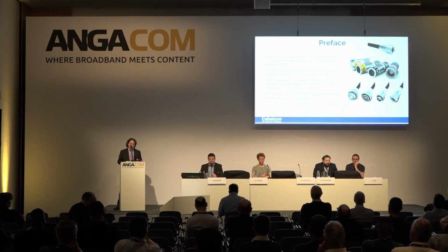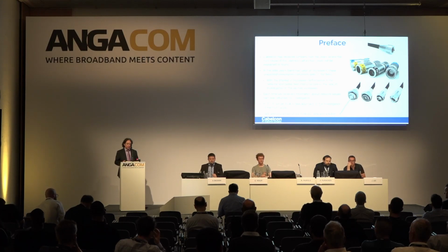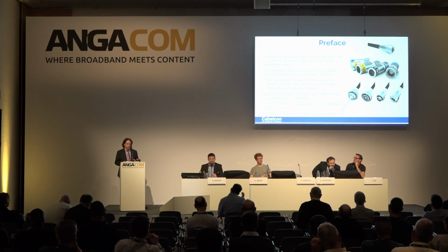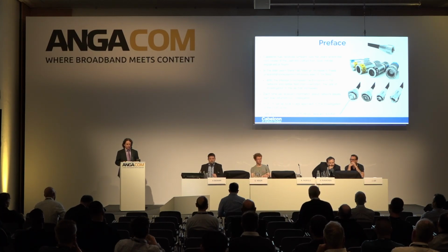In terms of quality of the connection between the modem and CMTS, this could be defined as a signal path that is not being impacted by noise or external signals disrupting the wanted DOCSIS signal. In the DOCSIS standard, there's the ability to adjust the modulation scheme being used between the cable modem and CMTS to maximize data throughput based on the quality of the connection. In simplistic terms, the lower the noise and interference, the more complex and spectrum-efficient a modulation scheme can be used. The higher the noise or interference, the less complex signal must be used, limiting the data throughput.